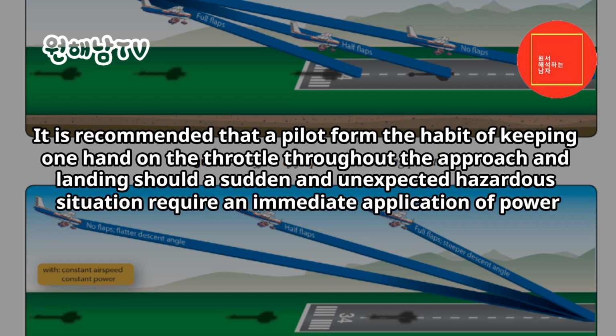It is recommended that a pilot form the habit of keeping one hand on the throttle throughout the approach and landing, should a sudden and unexpected hazardous situation require an immediate application of power.